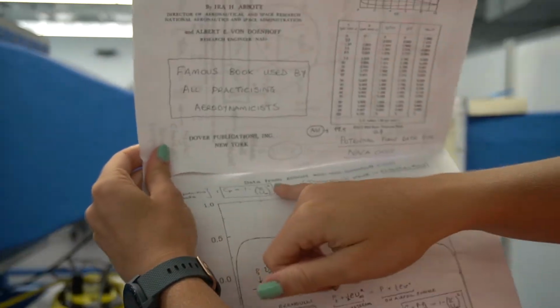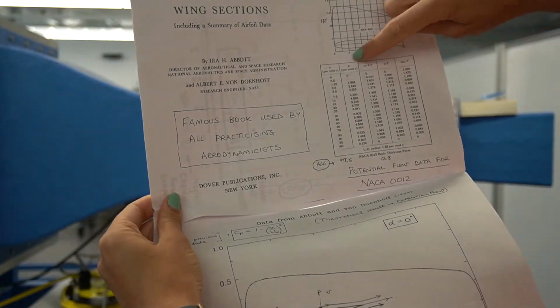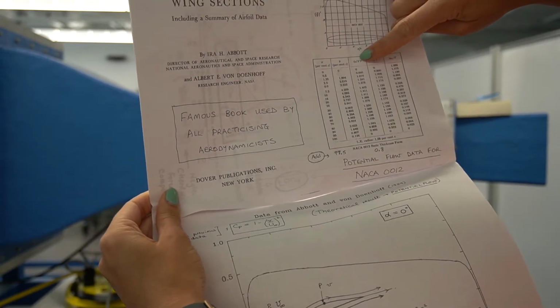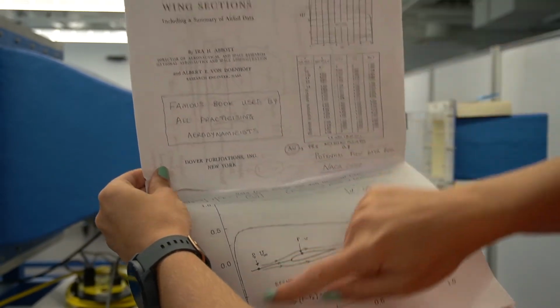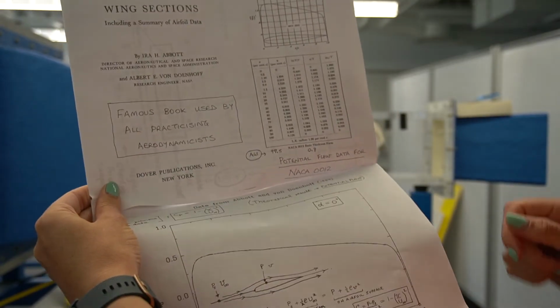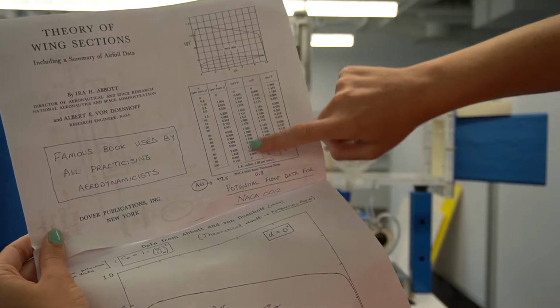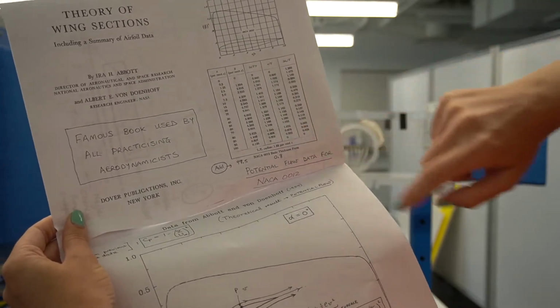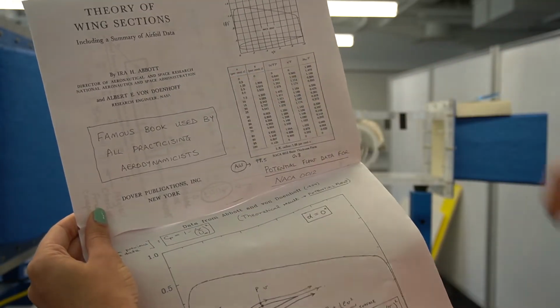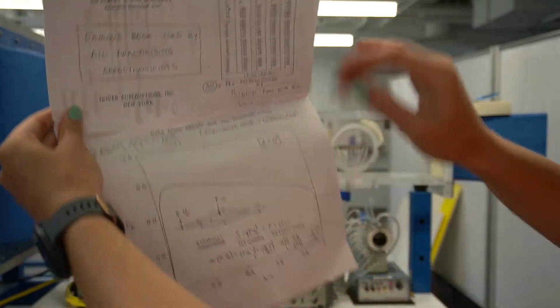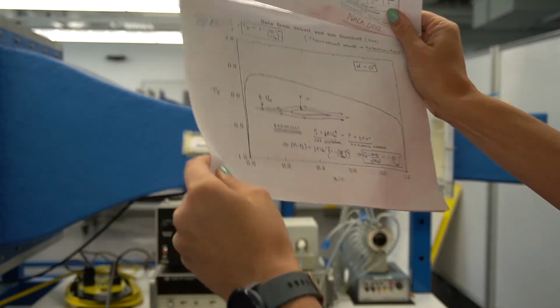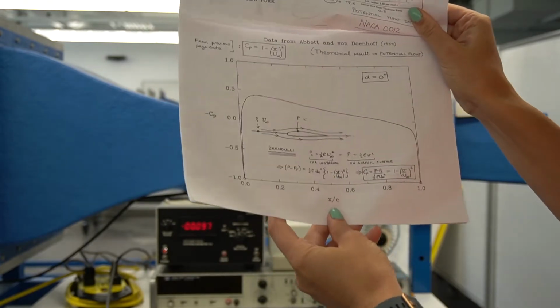So we're inputting it into this equation directly from this third column. So at home, you can reconstruct this plot by yourself. Your CP is going to be equal to 1 minus this third column. And you can see you've got X as a percent of C for your location. So you're going to have negative CP and X over C.